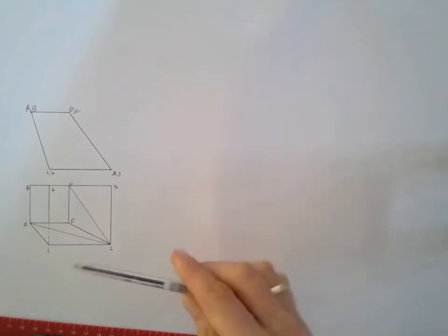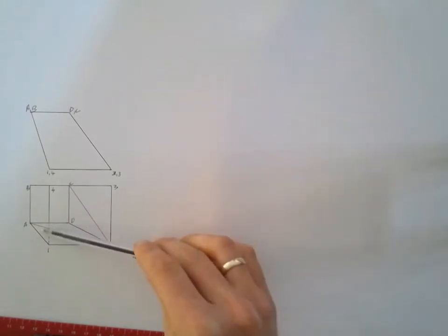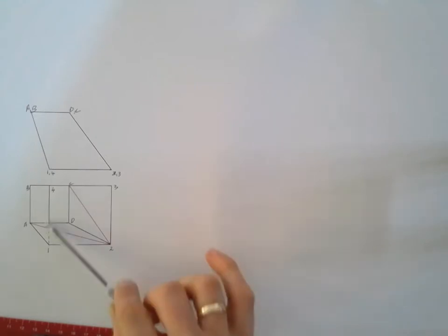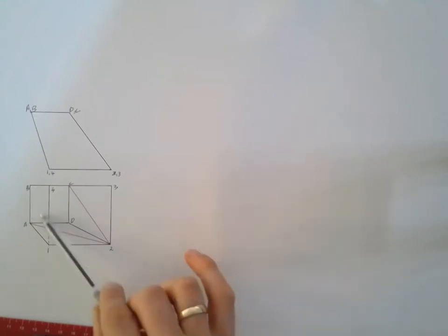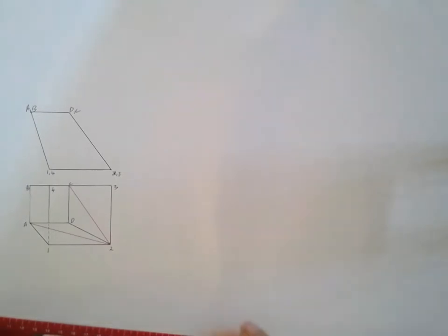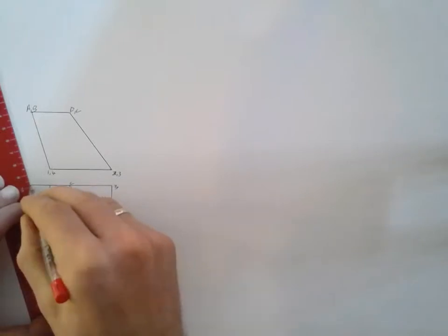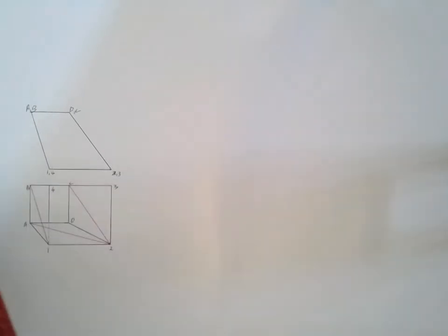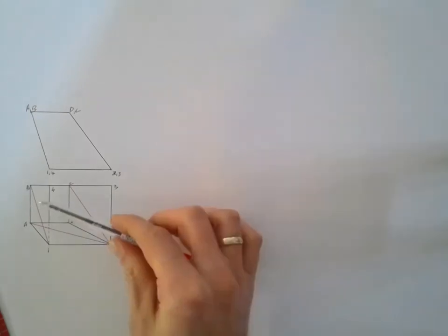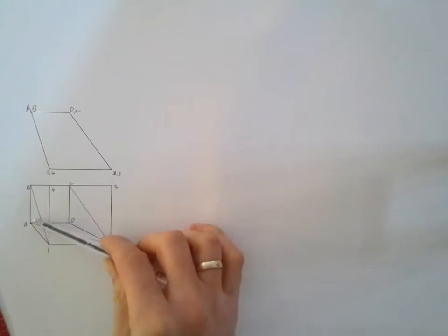Now the surface over here, even though it's angled away from you, you're still just going to do the exact same thing again. Here I joined a top point to a base point to create 2 triangles. Here I joined a top point to a base point to create 2 triangles. This surface here, I'm going to again take a top point to a base point to create 2 triangles. It's going to cross over one of the other triangles, but that's fine. It still triangulates that one side. Now that side has that triangle and that one over there that you can use for your development.